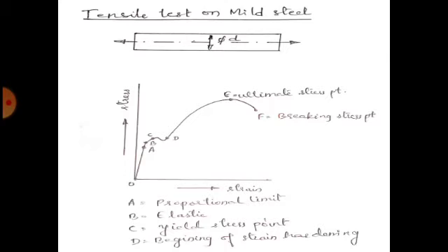At point D, the specimen regains some strength and higher values of stresses are required for higher strains. From region D to E is region of strain hardening. After E, the gradual increase of length of specimen is followed with a reduction in area. At point E, the stress attains its maximum value and is known as ultimate stress. After that, neck is formed and diameter will reduce. From point E to F is region of neck forming. At F, the stress is known as breaking stress. A later consideration will show that the load required to break away the specimen is less than ultimate load. The stress is therefore reduced until the specimen breaks.